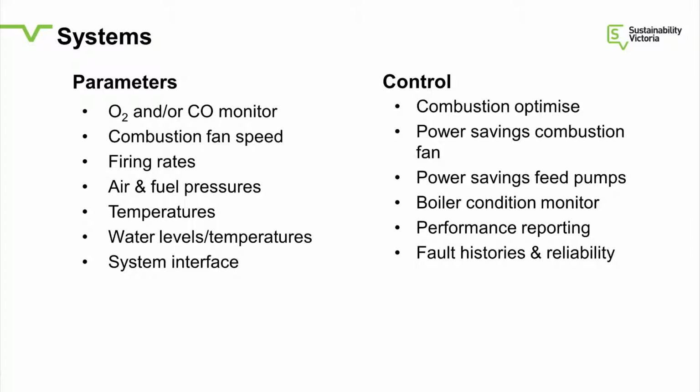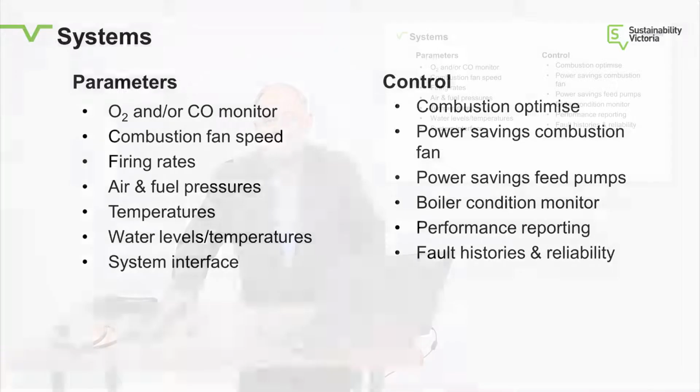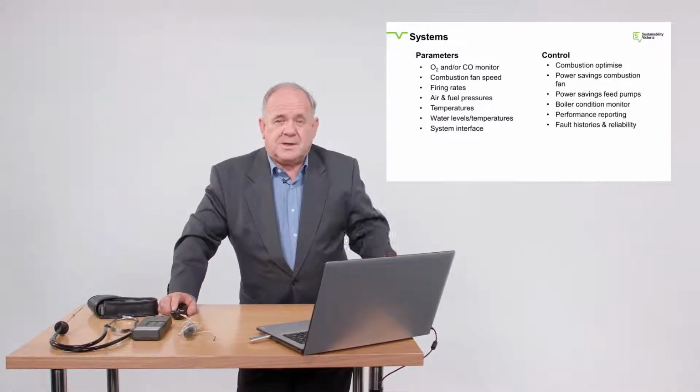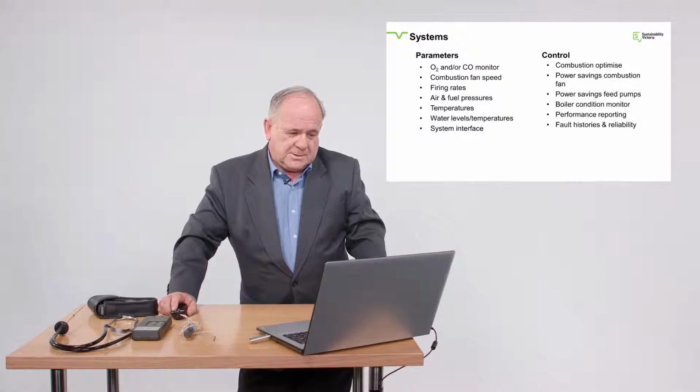The temperature, it's certainly worth monitoring the temperature of the exhaust, because really that is an indication of how healthy the boiler is running. If, for example, the temperature starts to go up significantly and you'd expect it to be 200, 220 degrees and it's 300, for example, it may mean that you're getting combustion bypass within the boiler. So the tubes may be failing and you might be getting a lot of energy bypassing the tubes and going to the exhaust. Very inefficient. That can add massive amounts to the operating cost.